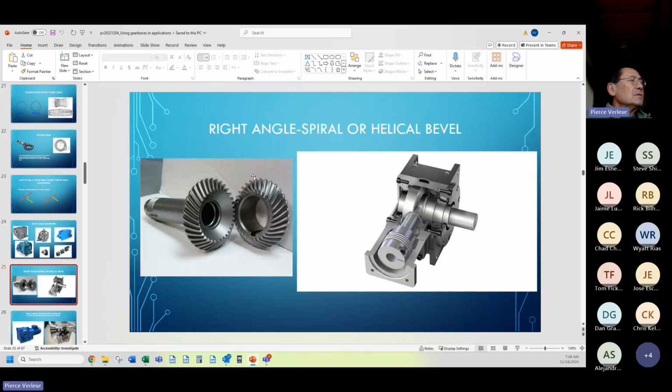There's the gearbox gearing, and that's how it manifests itself in terms of the total gearbox. Here's your coupling and your motor input. This is your output shaft. This, by the way, is a 1-to-1. This obviously is a reduction ratio of greater than 1-to-1. Here we have torque multiplication, velocity reduction.